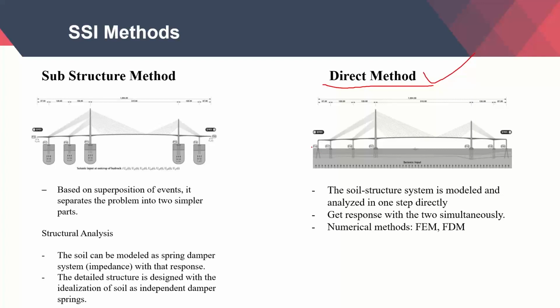That means the continuum method, or in other words, we will introduce the soil profile along the structure to check for the accurate deformations or plasticity along the soil due to the presence of the big structures. Numerical methods like FEM, finite element, and FDM, finite difference method, are very strong and astutely connected in the fact that you will get very accurate results based on your immediate requirements. And the entire soil structure system is modeled and will be analyzed directly in one step.